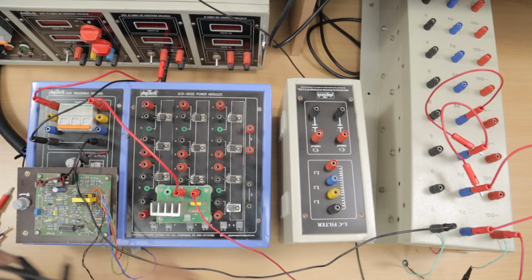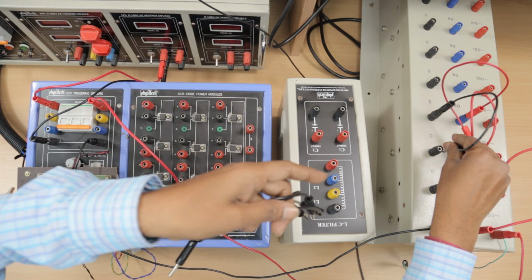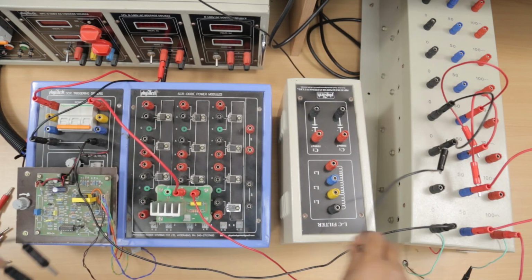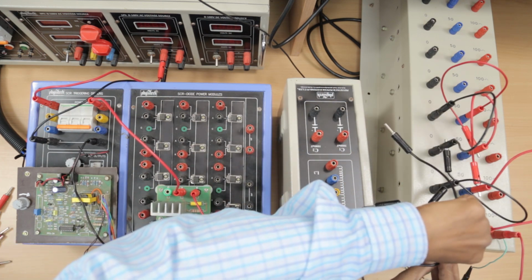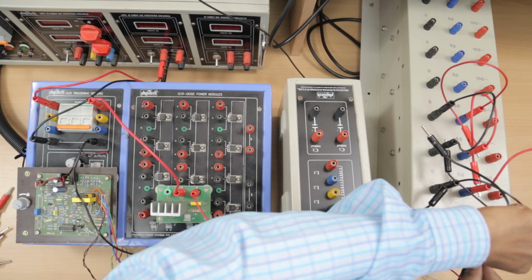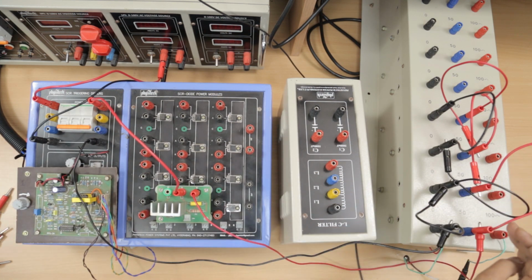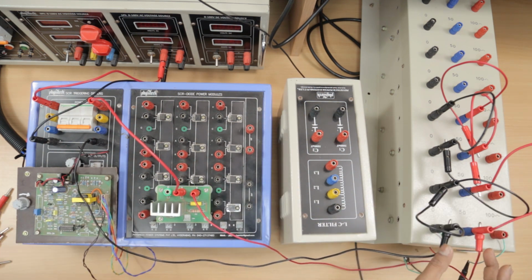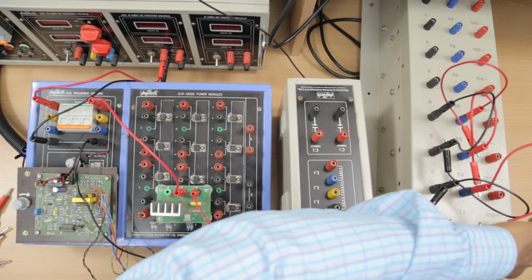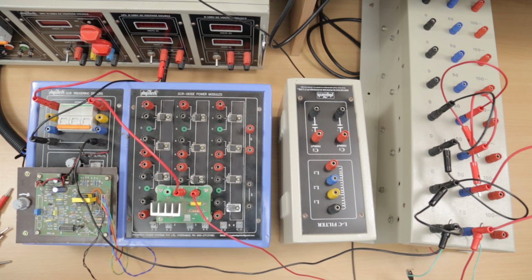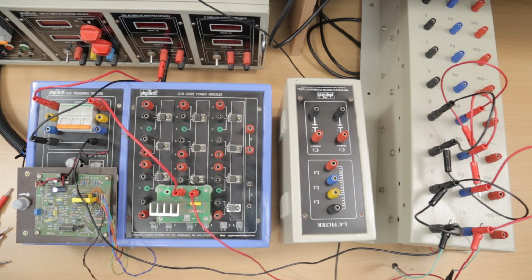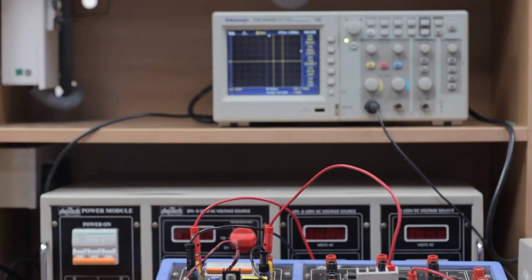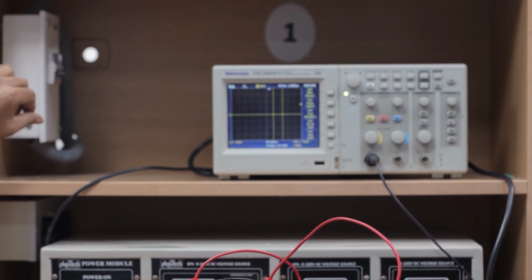And the remaining zeros also join. Now between 0 and this 50 terminal, four 50 ohm resistors are connected in parallel. Now we'll get between the black and red terminal a resistance value of 12.5 ohm. Observe this probe terminal as the positive terminal and this as the negative terminal. Across the resistance, we are measuring the voltage in the digital storage oscilloscope.